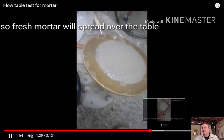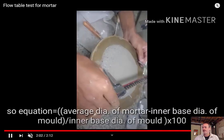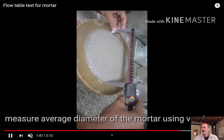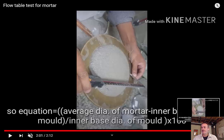We know the initial diameter, so we have a change in diameter. So there's the change, there's the final diameter with the calipers. And then we use our calipers to figure out the average diameter. So here's the equation to find out your total flow. What you have is the average diameter of the mortar minus the inner base diameter of the mold. So what that means is how much did it change? It's your change in diameter divided by your initial diameter, which would be the base diameter. Multiply it times 100 and it gives you a percentage.